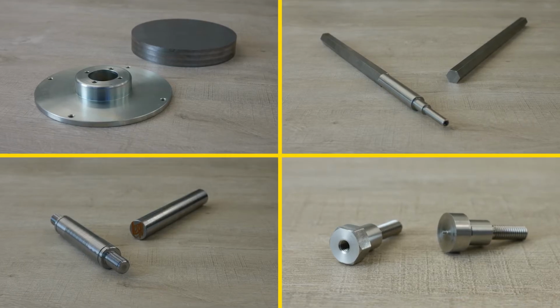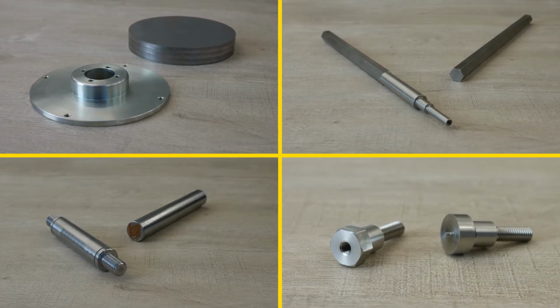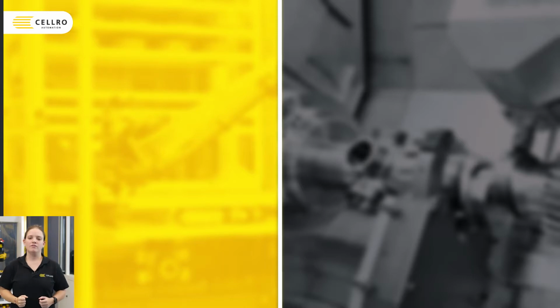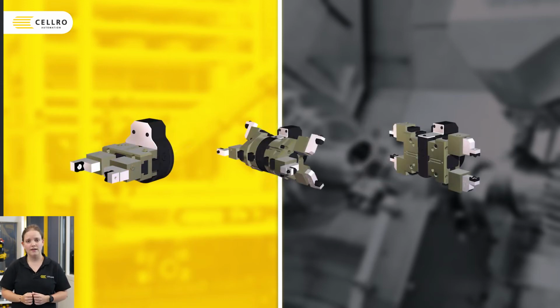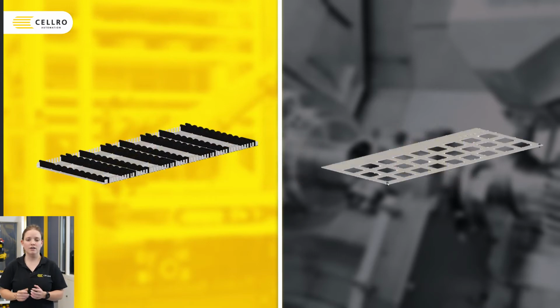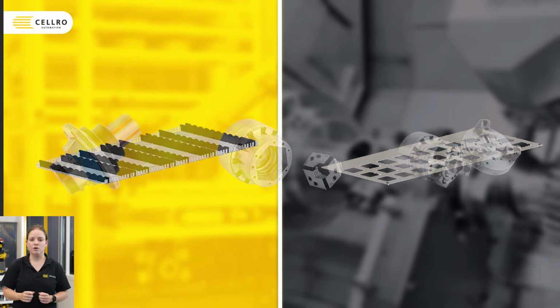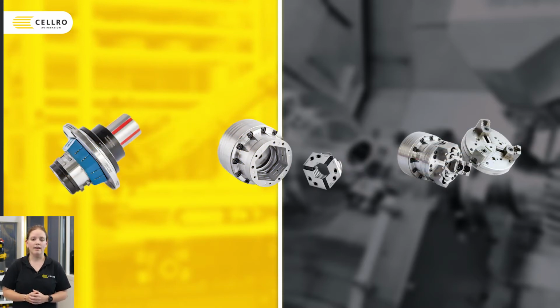And I hope you may recognize some of these products as similar to your own and know that we can handle all of these. I will give you an overview of all of the functionalities using this picture, and now it is empty, but we'll start filling this with all robot handling options. First, we start with the robot configuration, and this is the product shape and size, the gripper type, and storage options. And on the machine side, the machine configuration, you may have a 3-point clamp, which opens either inward or outward, or a collet clamp, or maybe a mandrel. Now, this collet clamp we'll discuss more later.